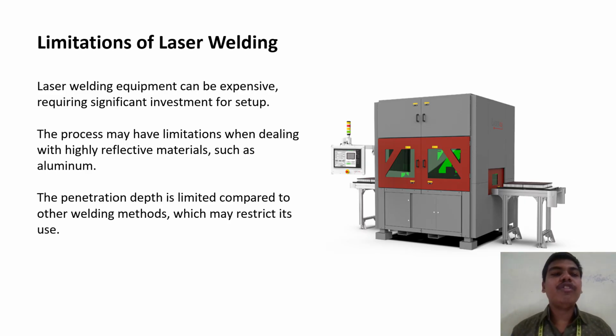Limitations of laser beam welding. Laser beam welding equipment can be expensive, requiring significant investment for setup. It can have limitations when dealing with highly reflective materials such as aluminum. The penetration depth is limited compared to other welding methods, which can restrict its usage.